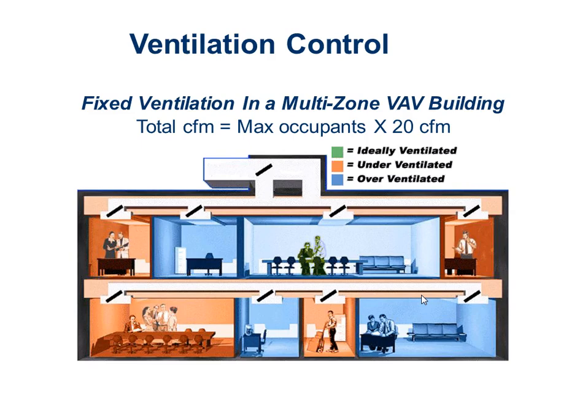So they may be set up correctly on a full design day, but then as we ramp the fans down, it's going to increase our percentage of outside air inadvertently, which costs us extra energy. The second problem with this kind of system is that we don't necessarily know where all the air is going. Bringing outside air into the air handler, but then as the individual zone dampers modulate back and forth, some spaces become overventilated and some spaces become underventilated.